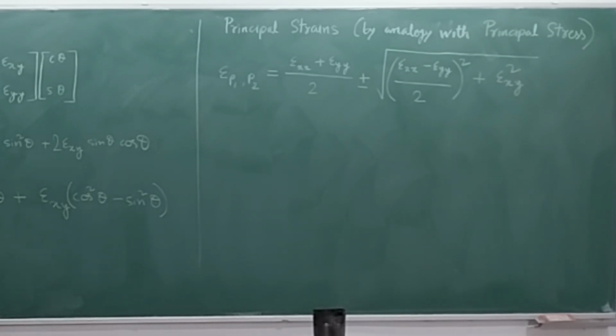Okay, because stress intrinsically is associated with the definition of traction. Traction can be defined on a certain plane. For strain you only need directions. You don't need planes. And then Mohr's circle can also be drawn, because Mohr's circle is motivated only by the geometrical form of the variables. Here also you will have exactly the same form.